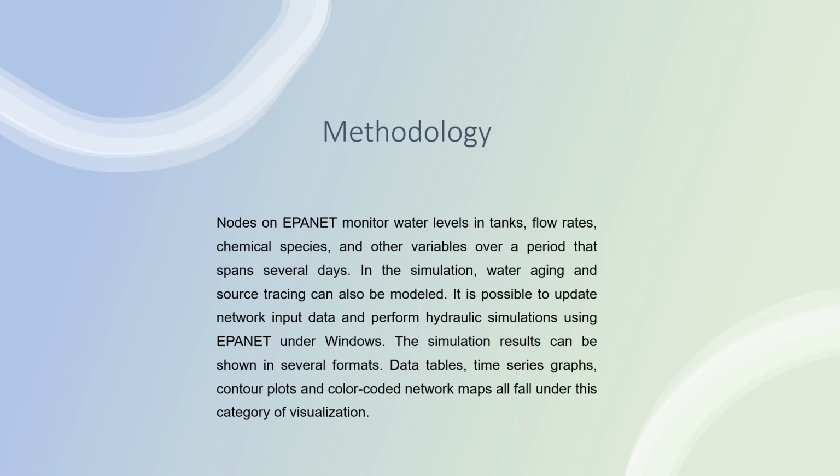It is possible to update the network input data and perform hydraulic simulation using Epanet under Windows. The simulation results can be shown in several formats. It can come in the form of data table, it can come in the form of time series graph, contour plots, and color-coded networks. All fall under this category for visualization.